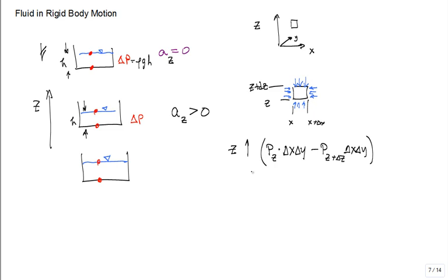also look for body forces, things that happen inside because it has some mass inside. What is the body force of interest? It's got a little W. What is the weight? Well, the weight is going to be minus, because it's in the negative z direction, the mass, which is the mass density times the volume, delta x, delta y, delta z, times g. Isn't that the weight of a little chunk? Density times its volume. The volume is delta x, delta y, delta z, times g is its weight.